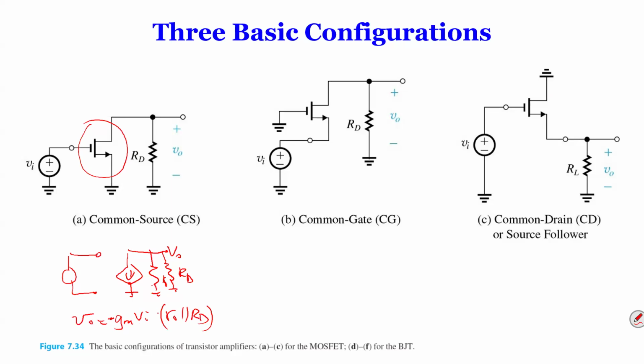And then the middle one, we're going to draw the equivalent circuit, but we're not going to solve it because we're going to solve it later anyway. So let's just start with the pi model. If we draw the pi model, you see what happens is the gate is going to be grounded. Like what I told you guys last time, identify the MOSFET and draw the small signal equivalent circuit of that amplifier and then connect everything to each of the terminals.